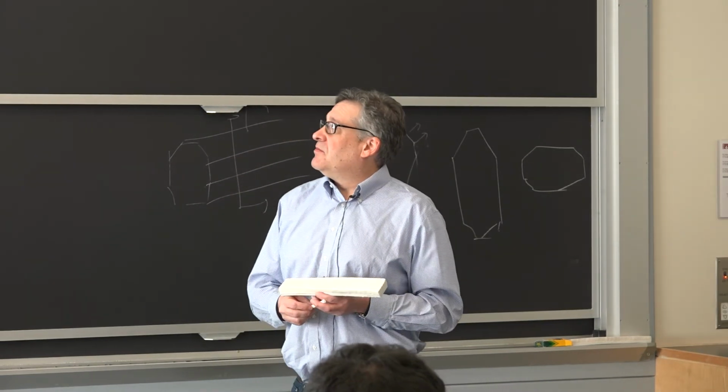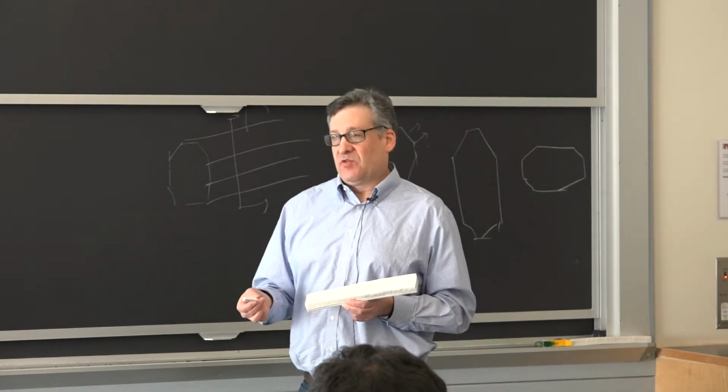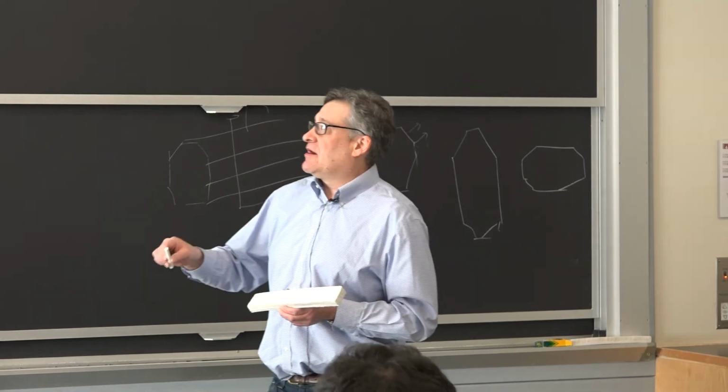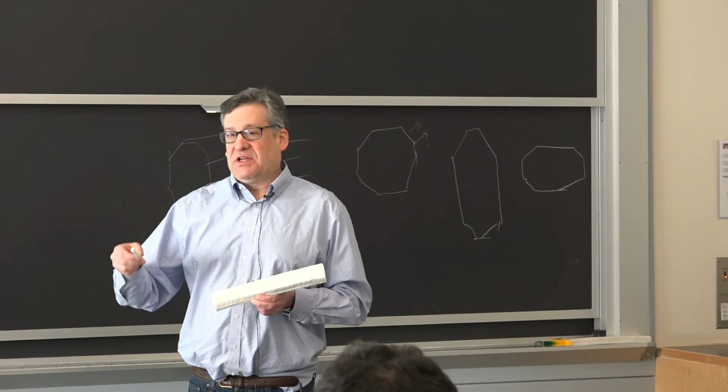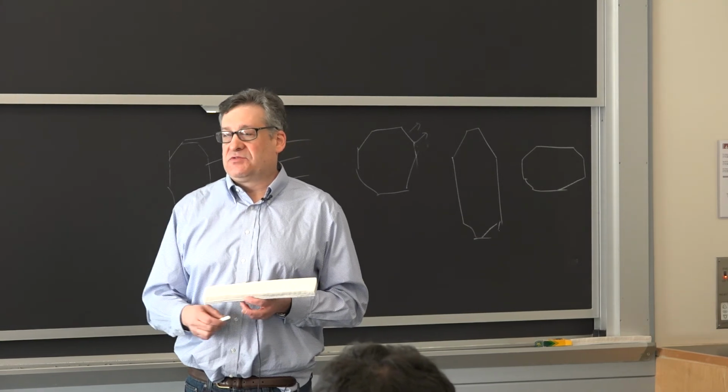So what the design variable becomes is the angle of the ply with respect to some global axis. So the optimizer will go through and calculate out the aggregate strain energy at different orientations of the plies, and then give you the lowest aggregate strain energy.